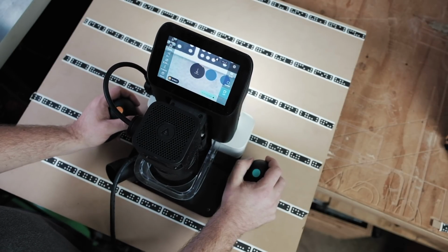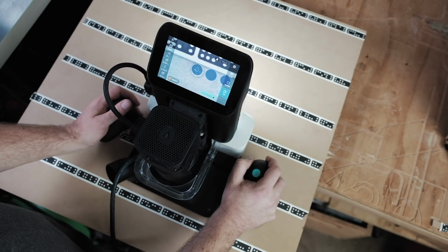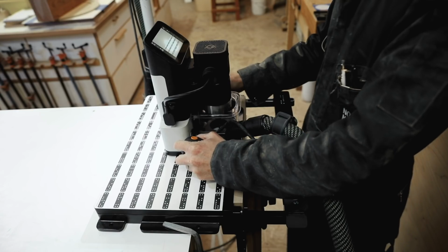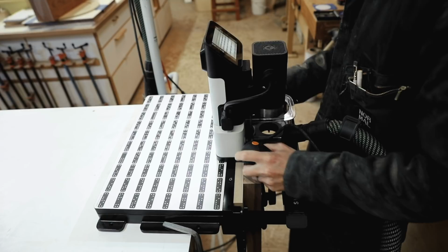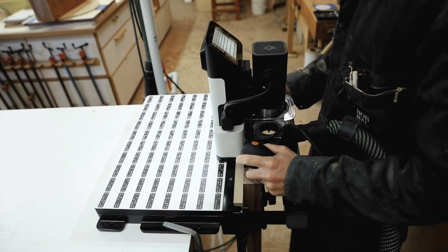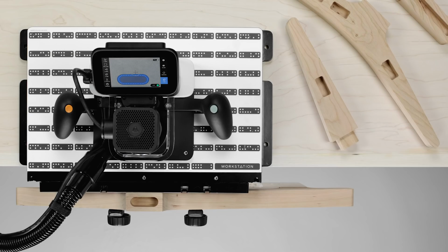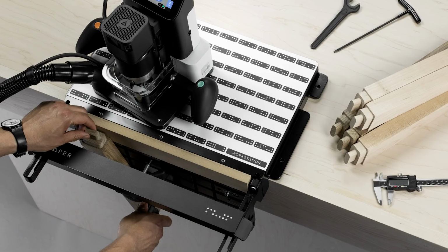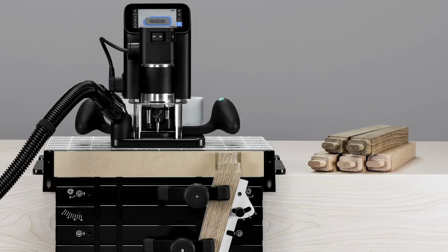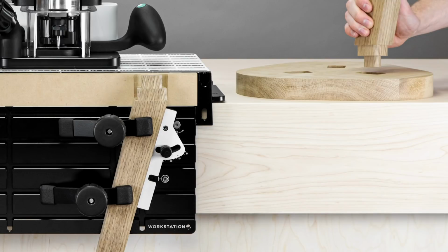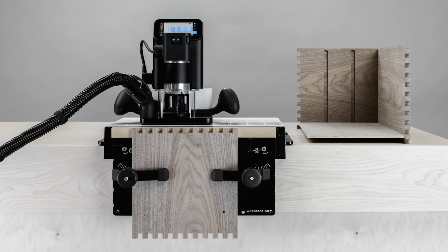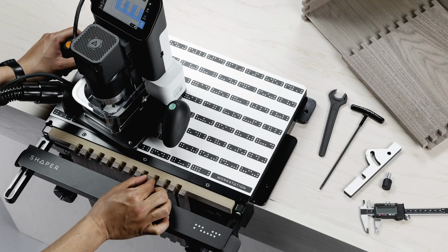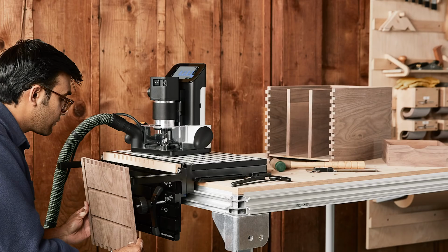We've made usability improvements across the board, lots of little tweaks. We'll go into a few of them in detail here. But the big focus here is the workstation. We've released the hardware product, the Shaper Workstation, which enables you to fixture geometry, awkward geometry, quickly, accurately, and repeatably, meaning that you can have a reduced burden, a reduced friction to setting up a job and getting cutting. You just clamp it to the workstation and you know you're getting 90 degrees, dead flat with your tape plane along the top, and you can just start cutting immediately.